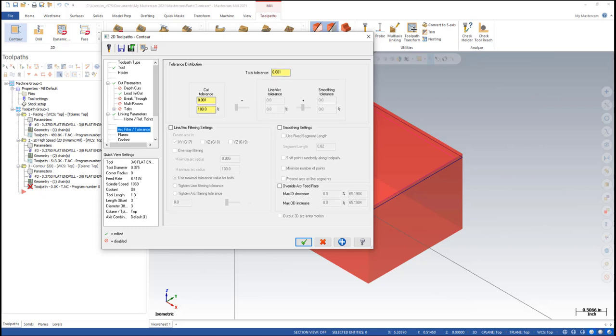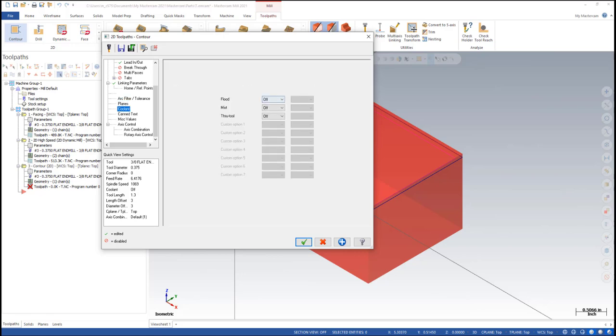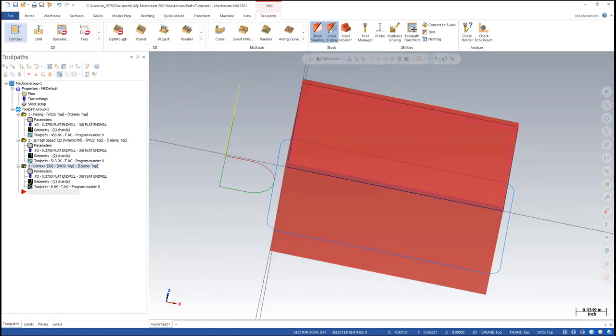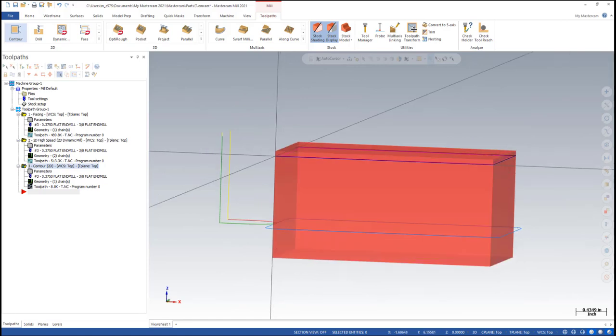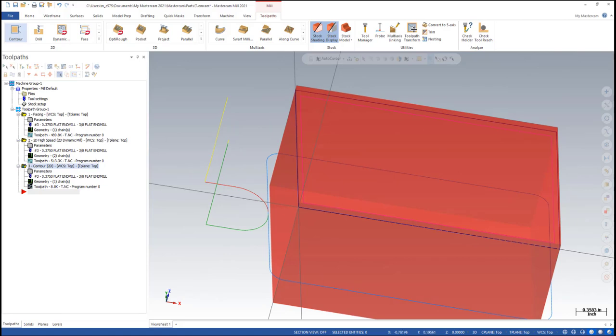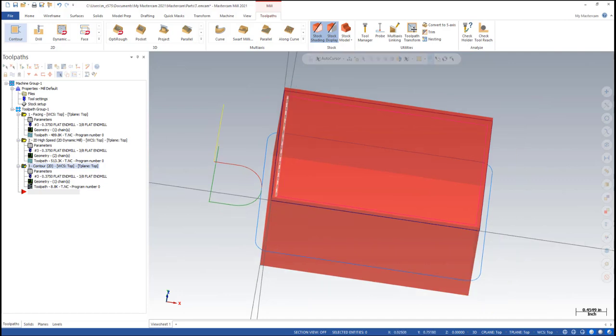That doesn't matter. We don't need to apply any sort of filtering on this one. That's fine. And finally, we got coolant, and just turn that on. So we'll hit green, and there's our simple contour. So it comes in at the 0.2 mark. It starts to feed down. The green motion is an entry motion. The red motion's a lead out, and then the yellows are retract in a rapid retract. So it comes down, it feeds in, it arcs in, and it goes around the part one time, and then it arcs out, and then it retracts, and then we should have our target geometry.